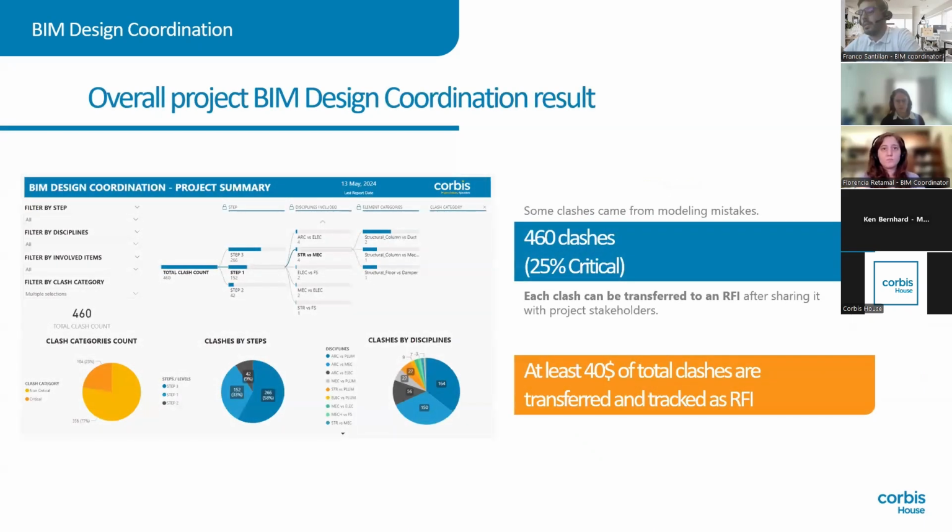Once we have all the information classified, analyzed, and grouped in Navisworks, we move all this information again to a friendly software such as Revit, and then we export all the clash information to Power BI, to merge, using some external software such as Speckle and Power BI, all the information regarding the criteria to group all the information, and also a 3D model that allows us to share this info easily and faster with the other people.